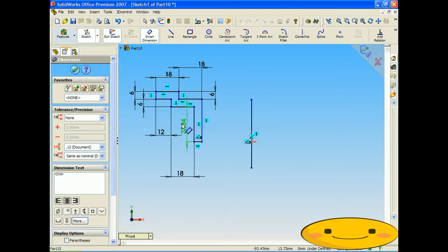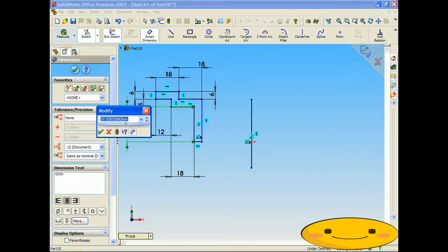And now we have this one in here. So you have to decide how long or how wide you want your rim to be. So right now it's going to be 6 millimeters, 6 millimeters, plus whatever we have going on here. So let's say that we want a 100 millimeter wide rim. We'd want 12, 12, and 38. So let's do that. Let's make this one 38.